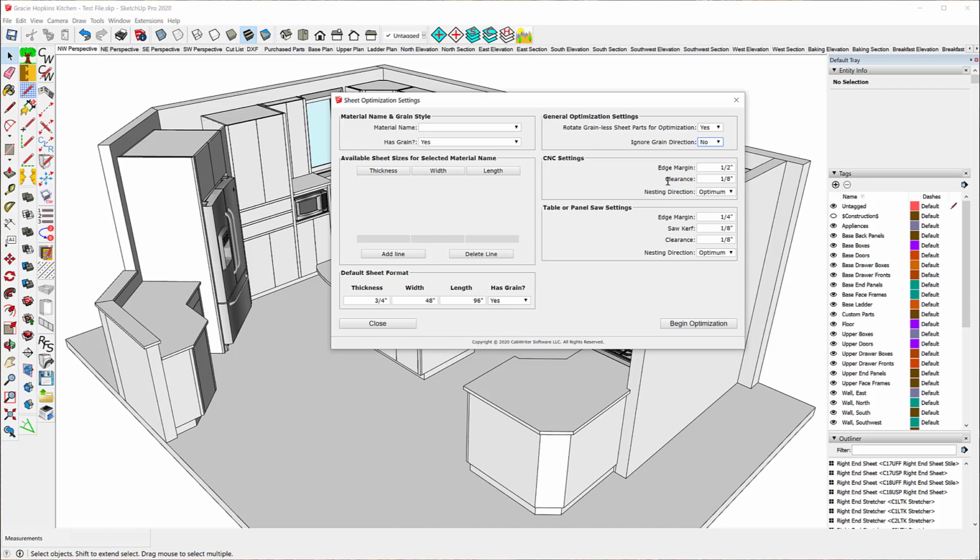The other thing is on the outside cuts that are in the middle of the plywood. We want to make sure that when the bit is cutting one part and then it comes back and tries to cut the adjacent part, we don't want it to accidentally be changing even a small amount the size of the previous part that was cut. So we want a clearance added to the diameter of the cutting bit, and that's what this is. I made that 1/8 inch.